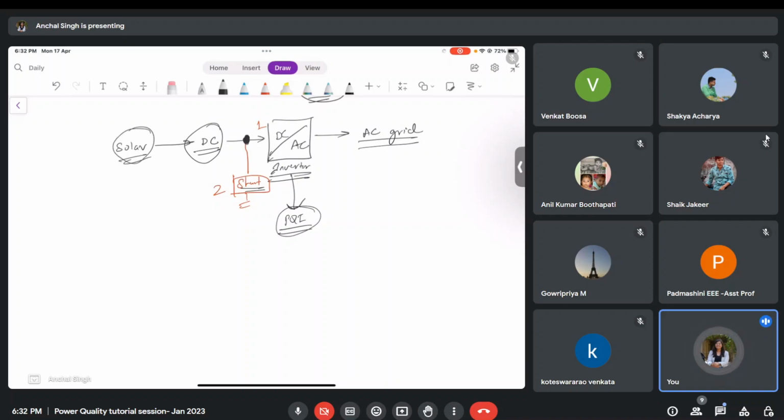that when solar comes into picture, you do the maximum power point tracking, right? So there is a controller and a converter involved there itself, so that the nature of current that is coming from that is not very constant, and you need to take care of certain power quality problems specific to the field of solar. So this shunt compensator was serving that purpose here.